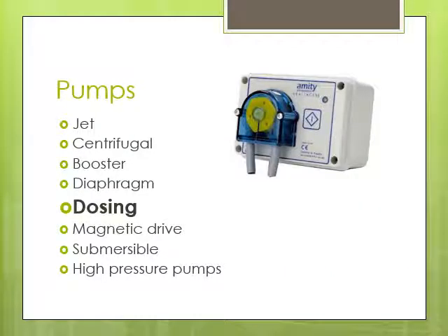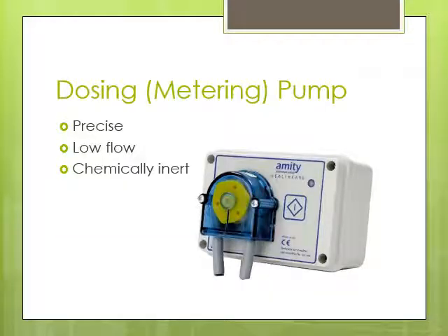Another type of dosing pump is called a peristaltic pump. Essentially, there's a wheel in here that has little nylon rollers in it, right? And as this thing spins, it squishes this pipe, and that pushes liquid through the pipe, which comes out the other end.